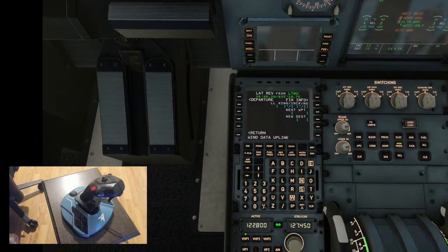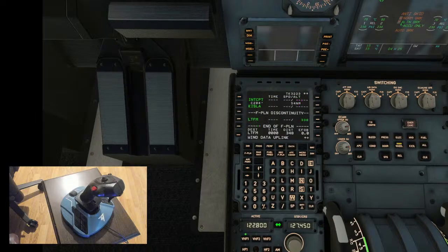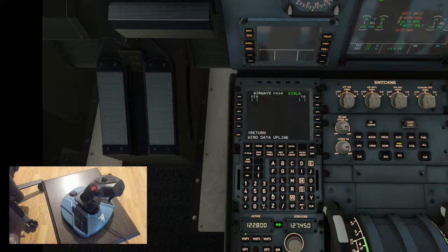From the WhatSim interface, I'm preparing my flight plan again. An initial departure today from Kayseri, runway 25. Here I insert runway 25, and initial standard instrument departure will be Kışla 1 Kilo departure. Here is Kışla 1 Kilo departure and transition on, and inserting. And after Kışla point, UA17 Yavru, UA17 Yavru point.